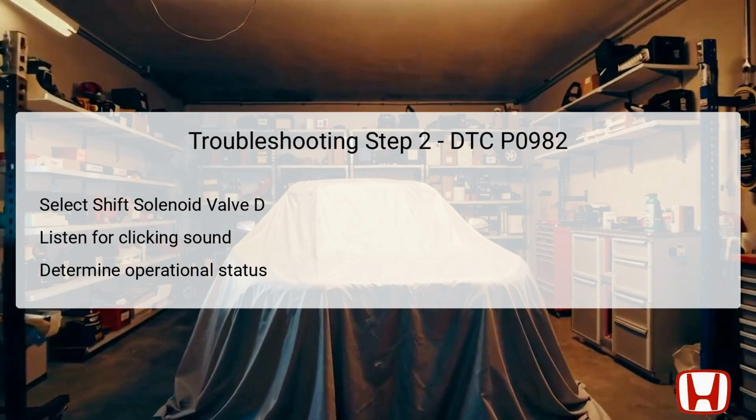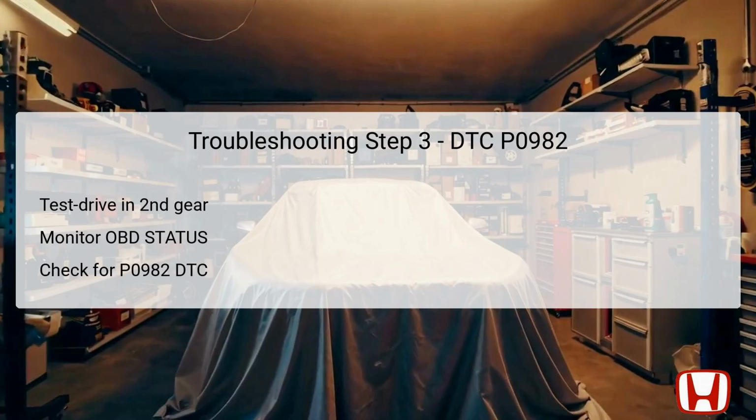If the clicking sound is absent, this indicates a potential failure in the solenoid or an issue with the electrical supply. Thus, confirming the operational status of the valve at this stage is critical for guiding the subsequent steps in the diagnostic process.